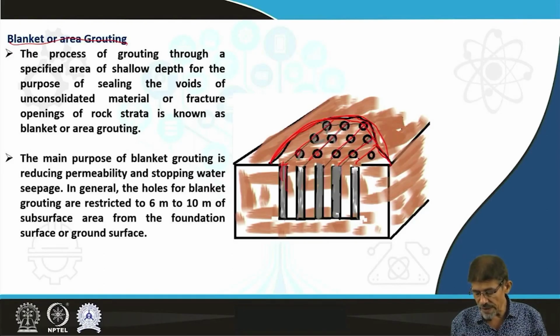In this way we are going to cover this whole area which is recognized as defective and fill these cement grouts and others, creating this type of barrier and strengthening of strata through suitable and successful grouting hole distribution along with grouting of the area.